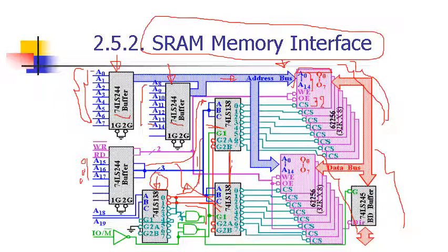But if you need to access this, you will have to activate only the upper decoder. So when the upper decoder is active, these 3 zeros go to here, making this 0 line low, activating this page. If you provide A0 through A14 all zeros, you access this memory location.